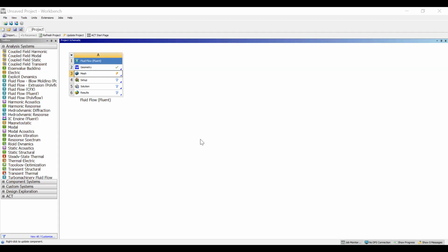So there you go. You can see our surface is loaded here. So we'll go ahead and go into the XY plane again. You can see it. And we're going to click on our mesh. So there that is. And then we're going to go ahead and right click on that, insert method. You can see it just comes up with, we need to select the geometry. I'm just going to click on this face.